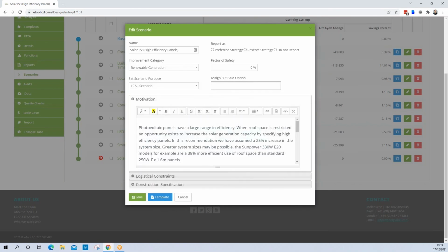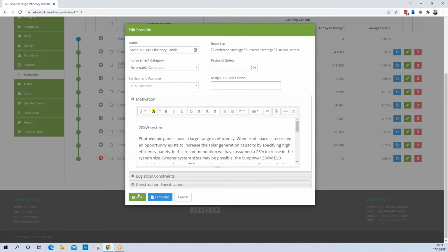It talks about the 20 kilowatt system. Of course, you have to do your generation capacity. This will come from PVWatts or any other solution you use to estimate your generation capacity due to your location, your solar radiation, your shading, your maintenance, all of that, the longevity of your panels, the technology.